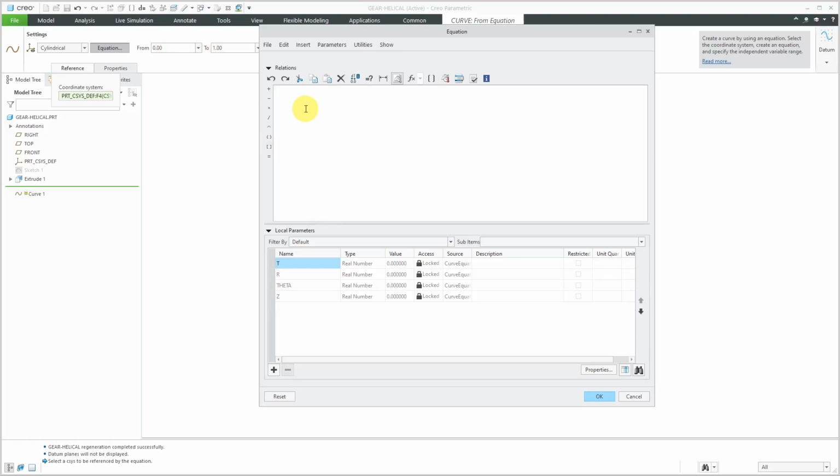And the first thing that we're going to do is calculate an additional quantity, gamma. And this is going to be equal to 2 times the arc sine of the thickness times the tangent of beta divided by 2 times the pitch radius.